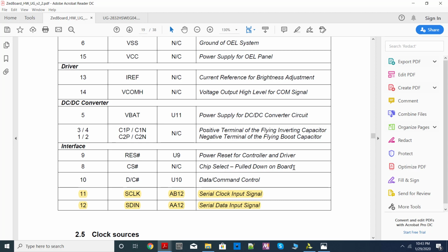You have to display characters, you have to display numbers, maybe you have to display pictures. How this information is communicated between the Zynq chip and OLED happens through this interface. Now these are two wires actually coming from Zynq to OLED, and from the naming it appears like this follows the I2C standard. Please refer to your lecture slides to know more about I2C, the inter-integrated circuit communication protocol, which uses serial clock and serial data, only two-wire communication.